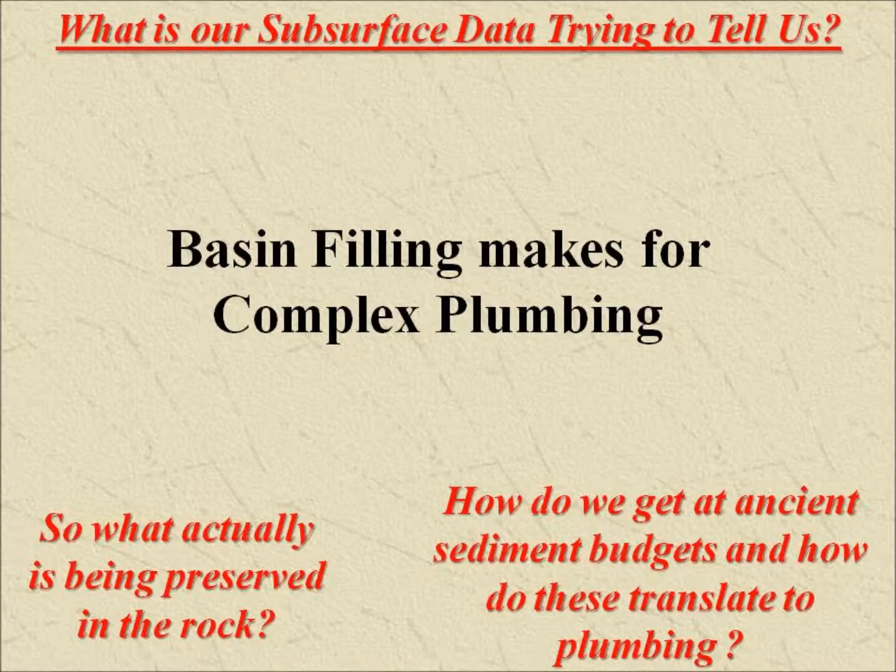But that said, picture yourself drilling a hole in a big aeolian sand. It looks like some big uniform body of sand where there should be an even sweep between the wells. But right through the middle of it, there's this little windblown armored lag line right along the path. You pump water here, it's going to go straight through that, an order of magnitude faster than it's going to go through the rest of the fine-grained sand.